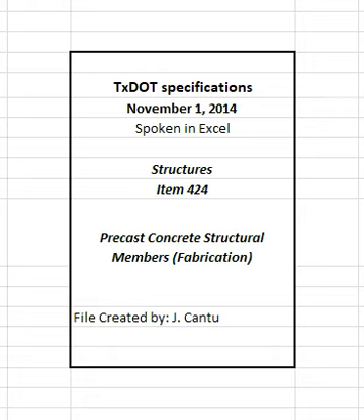Maintain forms sufficiently mortar tight to prevent damage that requires repair to the finished product. Where sections of forms will be joined, an offset of 1/16 inches for flat surfaces and 1/8 inches for corners and bends is permitted. Longitudinal form joints in prestressed concrete beams are not permitted except for in the side forms of slab beams, deck slab beams, box beams, and X-beams or as shown on the plans. Do not allow vertical or horizontal gaps or offsets to exceed 1/4 inches between adjacent sections of built-up end headers. Check the grade and alignment of forms each time they are set, and maintain them during placement of concrete.